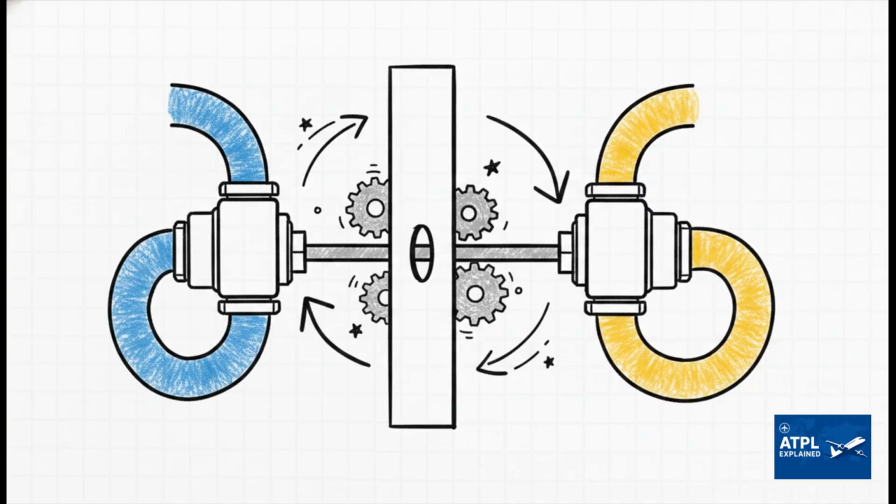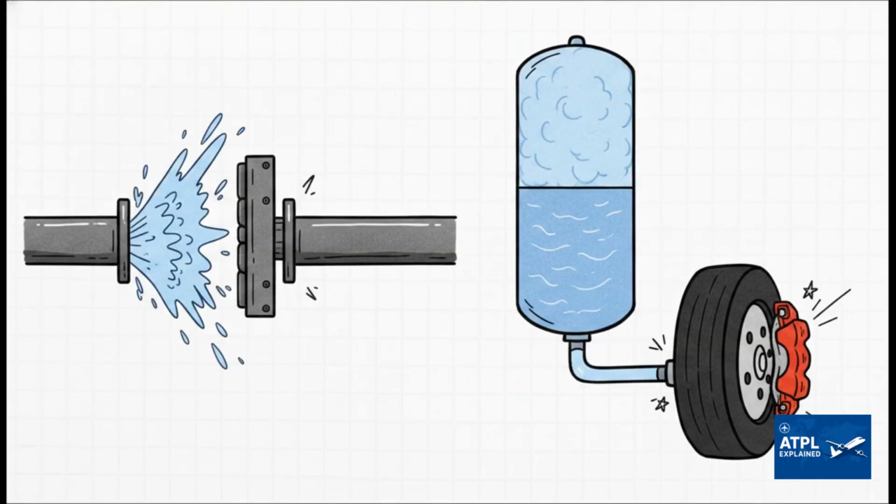Let's zoom in on number 2 on that list, the Power Transfer Unit, or PTU. Here is your golden memory trick for the exam. Power only, no fluid. A PTU mechanically transfers power from a healthy hydraulic system over to a failed one, without ever mixing the actual fluids between the two systems. It's essentially a hydraulic motor on one side, driving a hydraulic pump on the other. Pretty clever, right? All right, here are 2 more crucial protective components you really need to memorize.